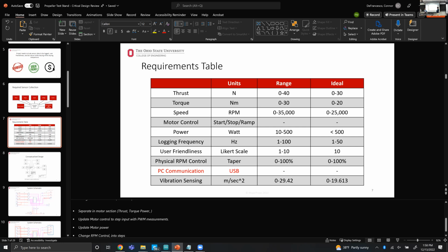You might have the difference between a vibration sensor and an accelerometer. I think it might have the driver or the code that tells you about the vibration on all 3 axes. Okay. I'm not sure, I know that it also works based on acceleration, but I know we have a vibration sensor specified and advertised as a vibration sensor, and an accelerometer. The accelerometer might not be sensitive to all changes of acceleration. It might have a filter inside, like every so many samples, just read one acceleration. Vibration sensors are for higher frequency. Okay, right? So there's a difference.